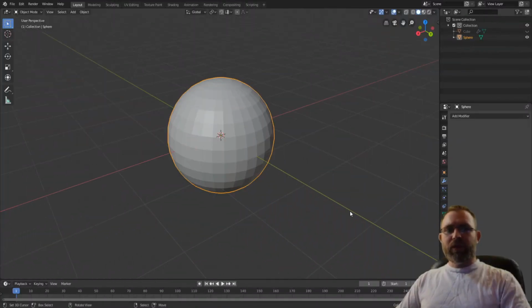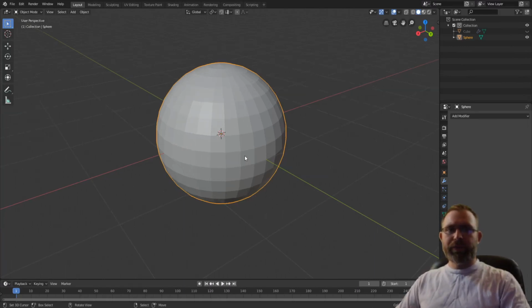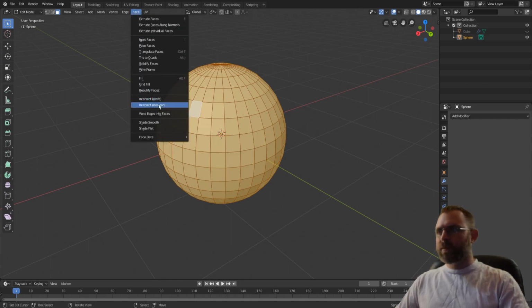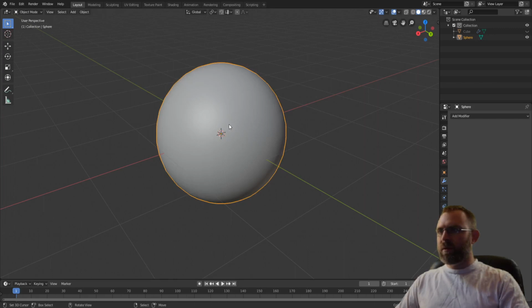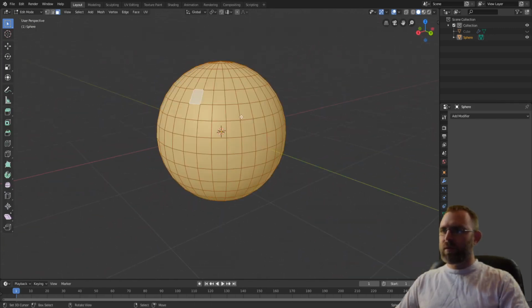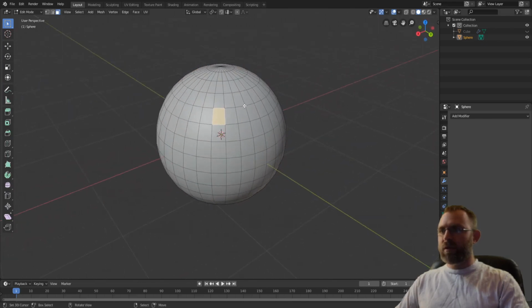Here we have a sphere like the sphere we had in our Unity scene, and you can see that it's got a bunch of faces similar to our cube. The trick with round objects like a sphere is to tell the mesh to shade the faces smoothly instead of drawing hard lines between them. When I set the face shading to smooth, the sphere suddenly appears to lose its faces, but as you can see in edit mode, they're still there. It appears that the hard edges have all disappeared, but they are still there. It's just a shading technique.